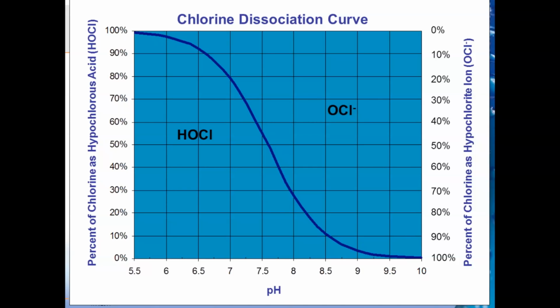So you can see on that bell curve that at a pH of 8.5, we would only be reading slightly more than 10% HOCl. The rest of that chlorine has changed species to OCl minus. And remember, it does not have the disinfection strength of the HOCl. Over the years, and we've seen this a lot, particularly because we're in the pump business, when people start adding sodium hypochlorite, in the past they added chlorine gas. Chlorine gas kind of assisted with the problem that they were seeing here.